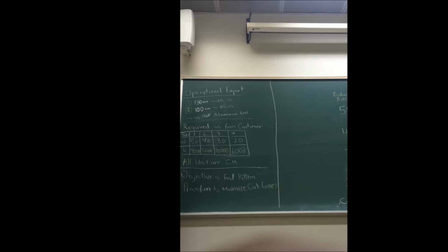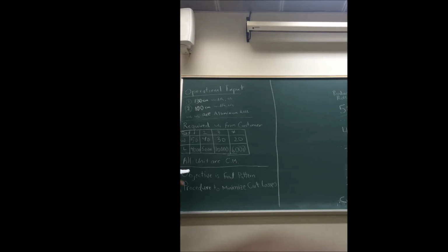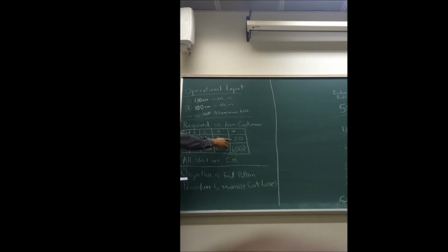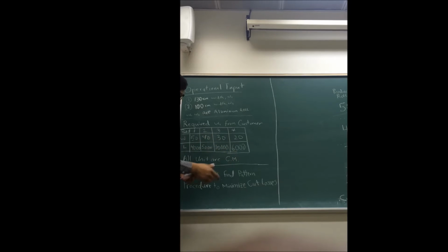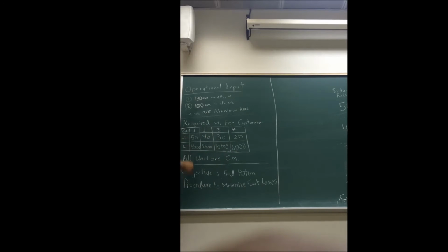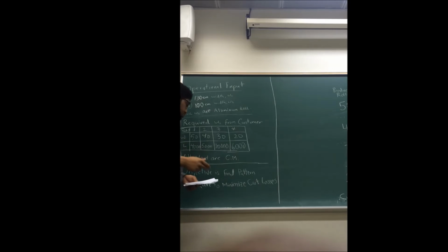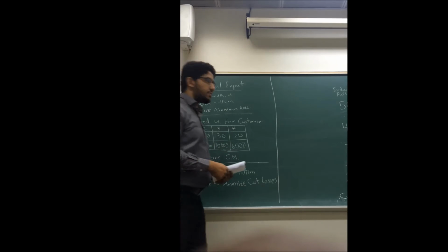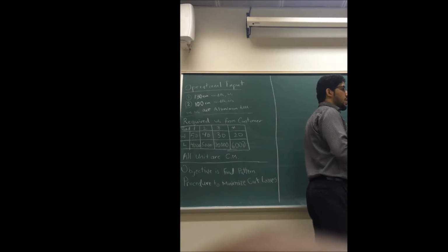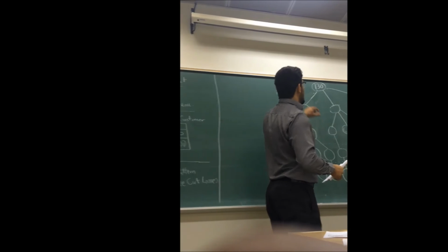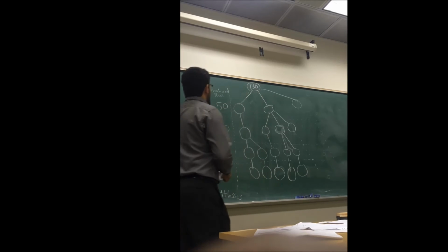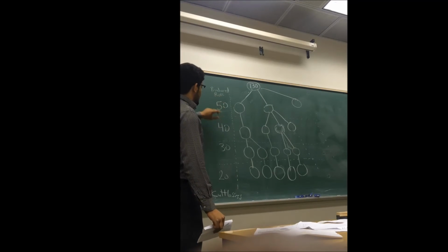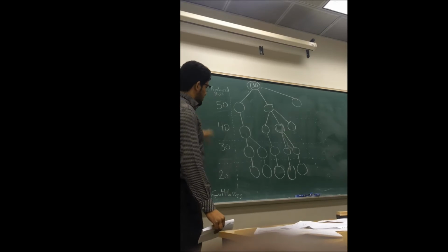In this example, there is a customer that required 4 types of width. We start with 50, 40, 30, and 20, and we have lengths which are 4,000, 5,000, 1,000, 600, and 6,000. I'm not interested in the length actually, only the width. Our objective is to minimize the cut losses. In our example, we're using the standard width of 130 centimeters, and we require the reduced rolls, which are 50, 40, 30, 20.